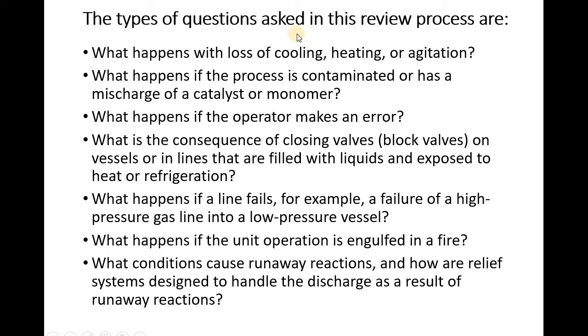Now, what type of questions do we need to have in our mind? So what happens if I don't have cooling? I already talked about it, right? And it could be also because of heating, by the way. What happens if the process is contaminated, right? And contaminated, causing some kind of a reaction and runaway reaction, causing a lot of vapor and pressure build up.